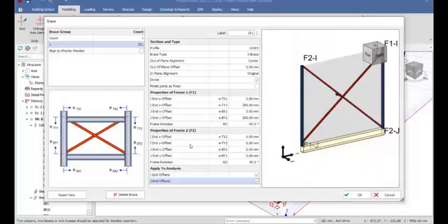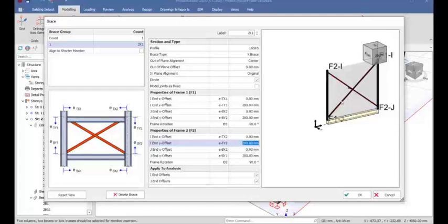the stanchion right there. The same thing is applicable to frame 2 too. The IN Y offset is to be 200, and 200 in the J end offset, just like this. So with this, we are done with the vertical brace.